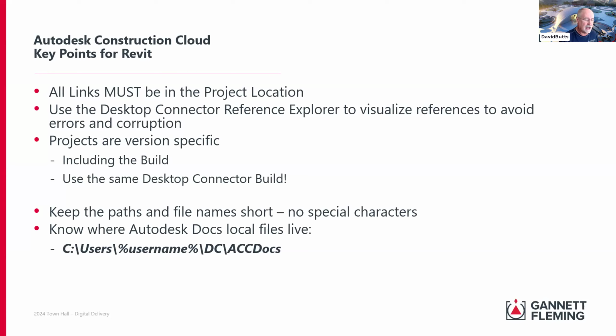But the Reference Explorer actually allows you to pick a file and say, show me all the links. It doesn't matter whether it's a Revit file or a DWG, but it shows you how files are linked into that one file. And this is how you track down when somebody's got a link that's outside of the environment, it's back to their local hard drive, but also if it's a bad link.